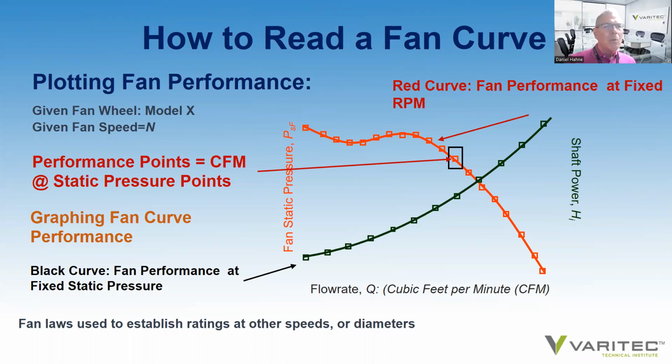And then in 1/10 of an inch increments, start adding static pressure. So as static pressure is added to the system, the new airflow rate is measured, and we notice that there is a reduction in airflow rate. And a curve forms as we continue to add static pressure until we reach the top of the curve, which is known as the stall point.